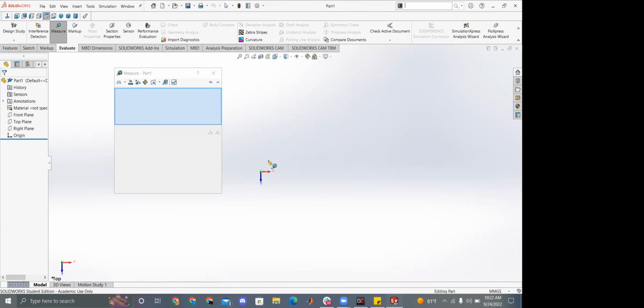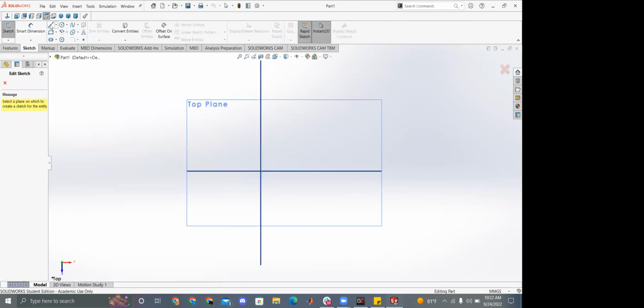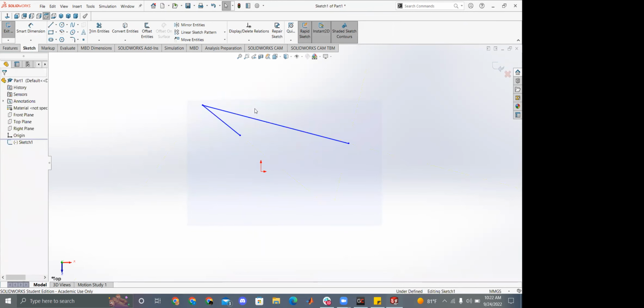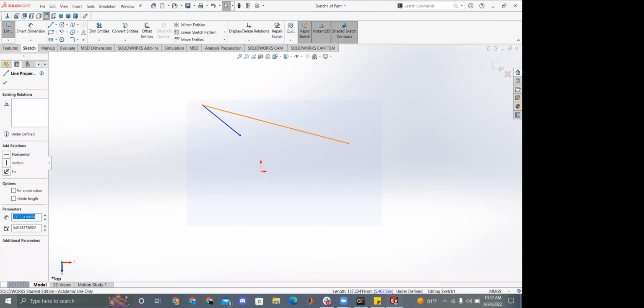But if you've enabled that setting, you'll see that. Let's open up a sketch here. Let's just put a line and say we want the length of this line, right? Oh, this zoom interface is covering it up. You can see we have the length on the left in millimeters in black. On the right, in blue brackets, we also have that dimension in inches. That's going to make it a lot easier to check your dimensions and measurements.